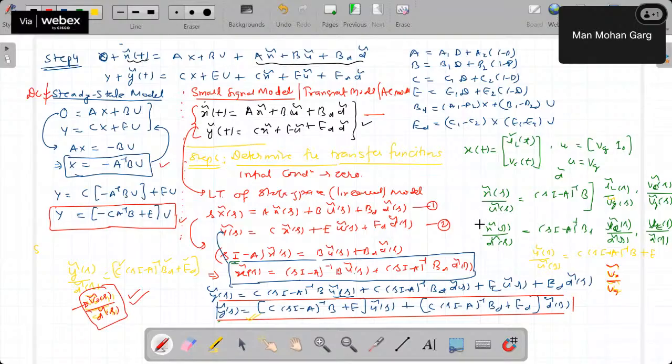control approach, then you need to fix the current. In that case you need this transfer function IL of S upon D of S. So it shows how variation in duty cycle will affect the inductor current. If you are using current control, then you need this transfer function. And if you are using only voltage control, then you need this transfer function. And if you are using multi-loop, which we will discuss in control system, then we need both transfer functions. So it depends upon what our requirement is, what kind of control we are designing, then we accordingly use the formula.